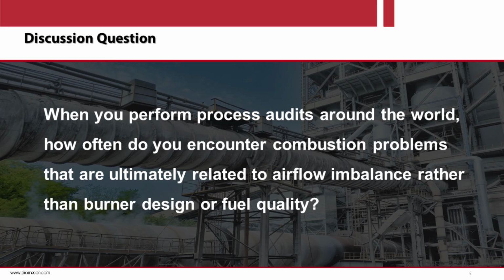While the airflow imbalance between tertiary air and secondary air impacts factors like energy consumption, coating formation, which comes quite lately, or CO emissions, which you can suppress by just adding more air. And these are more related to long-term efficiency parameters, and they are not immediate troublemakers like flame shape or primary air related issues.